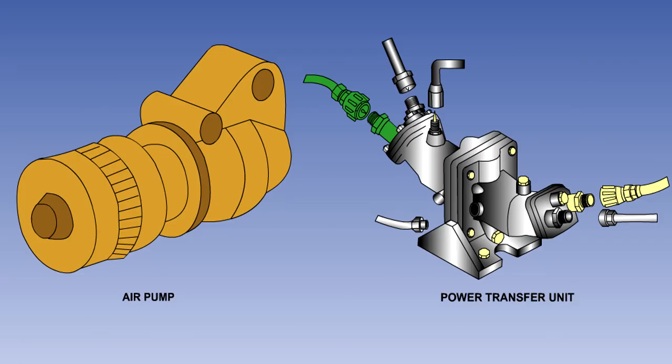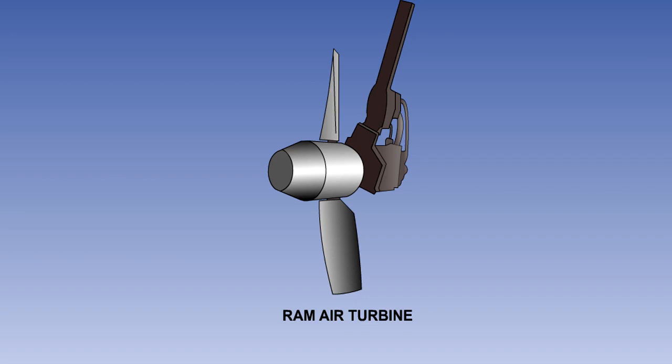The latter three pumps, the pneumatically operated pump, the RAT and the PTU, are usually used to provide a backup supply to an engine-driven pump, thus providing hydraulic system redundancy in the event of engine or EDP failure. The output of the ram air turbine will normally be used as a backup solely to operate the primary flight controls and brakes.